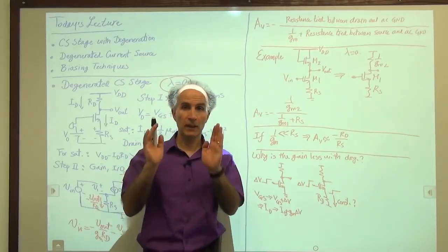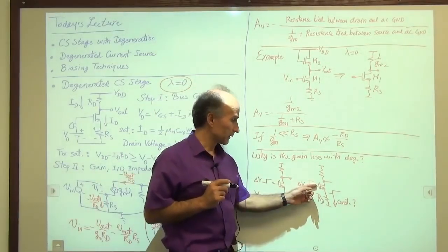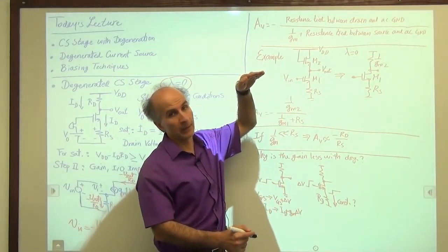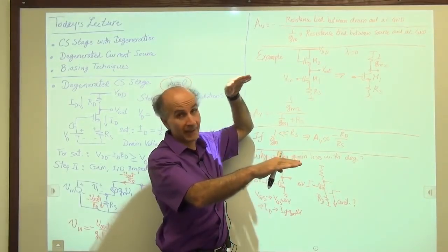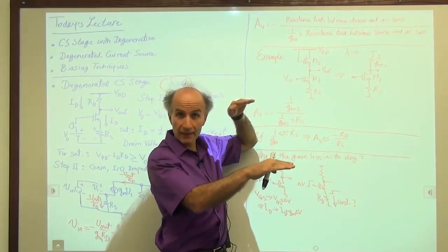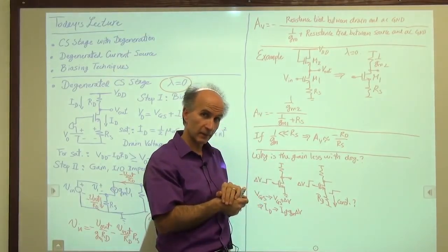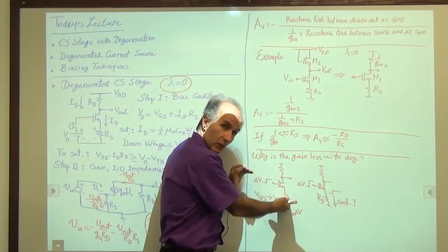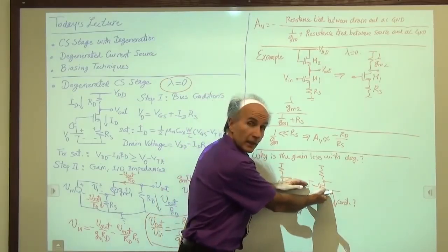All right, so here comes the interesting point. In this circuit, what we see is the gate voltage goes up. The source voltage goes up by some amount. That means that VGS does not increase by delta V. Right? Here, VGS increased by exactly delta V because the source was fixed, the gate went up by delta V. But here, it did not.